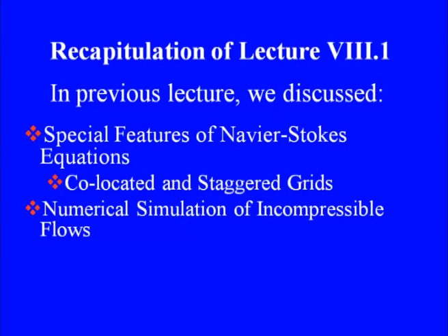And we briefly discussed the special things which are involved in numerical simulation of incompressible fluids, in particular that there is no independent equation for pressure. So, we must derive a Poisson equation for pressure which would ensure the satisfaction of continuity.